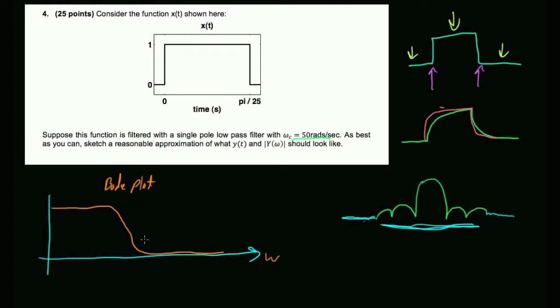You've got a system and you've got a signal. If you take the Fourier transform of a signal, we've been doing that all semester. If you take the Fourier transform of the system, you call it a Bode plot. But mathematically, it's exactly the same thing. Which is kind of cool, right? Signals and systems are really the same thing. If I give you a function, you could either think of it as an impulse response of a system and look at the frequency response of your system, or you could say, oh, it's a signal. Mathematically it's the same thing.